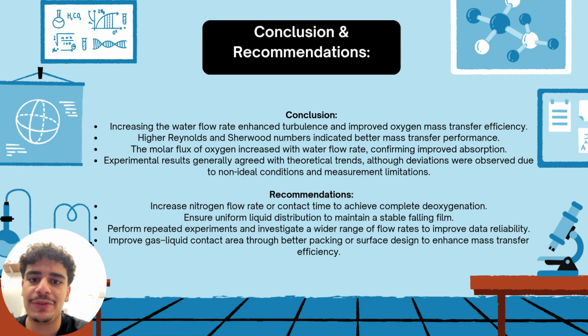Okay, so now moving to the conclusion and recommendations part. So for conclusion, increasing the water flow rate enhanced turbulence and improved oxygen mass transfer efficiency. Higher Reynolds and Sherwood numbers indicated better mass transfer performance. The molar flux of oxygen increased with water flow rate, confirming improved absorption. Experimental results generally agreed with the theoretical trends, although deviations were observed due to non-ideal conditions and measurement limitations.